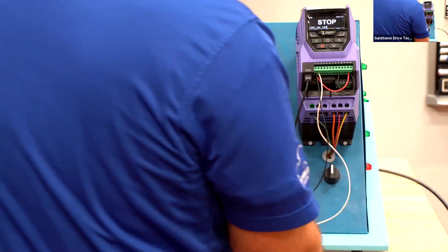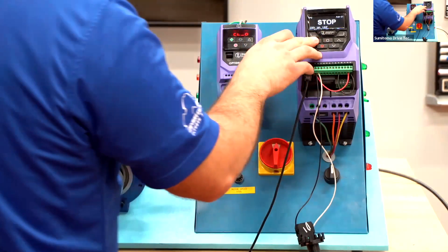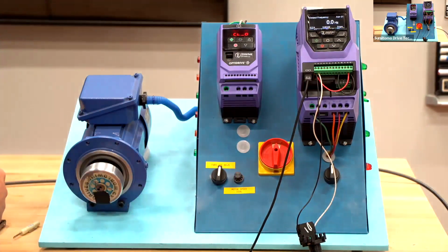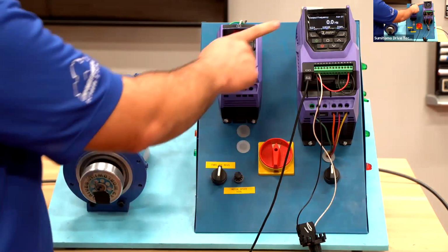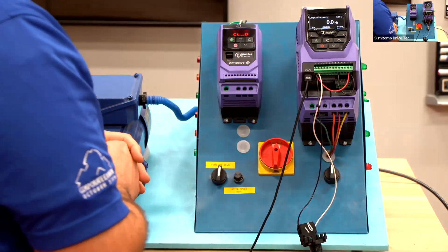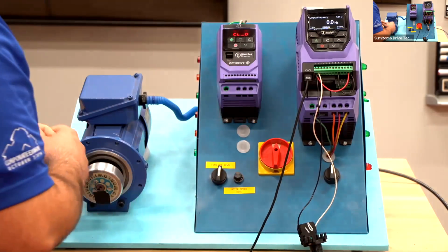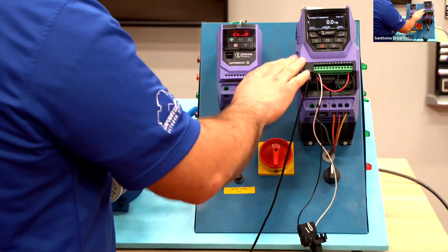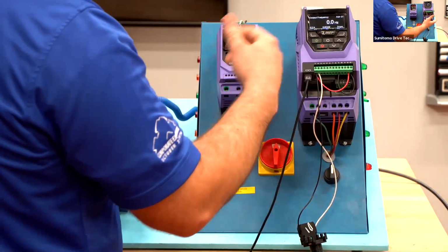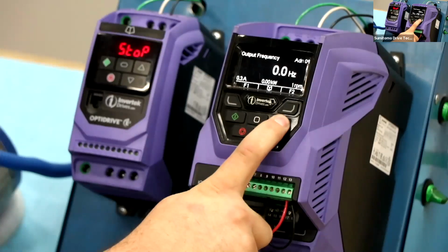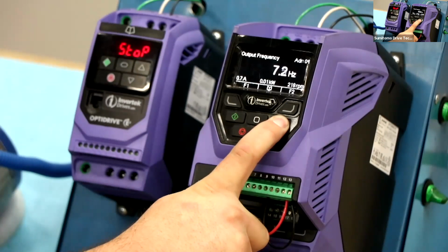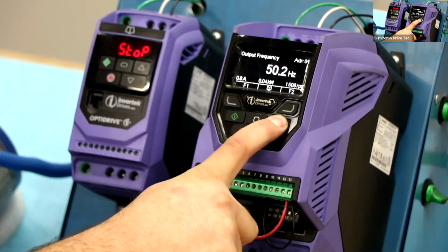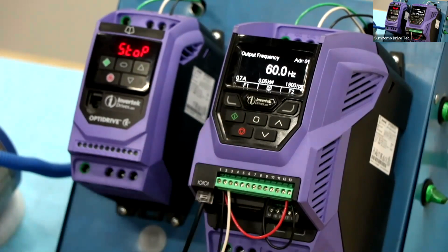So this circuit has to be closed. So we hit start. Now that we hit start, it's like the motor's not running. If you can see that there, the motor's not turning, but it changed the display. So what's the reason for that? The default setting on this is to start at the previous setting it was set to. Since this drive has never been used, it was 0. So what we can do now, we can come over and crank the speed up to the max of 60 Hertz, which is the 1800 RPM that we set previously. And now the motor is up and running.